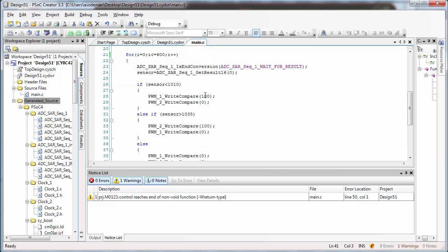So think about first what you would expect to happen. For example, if I would change this from 100 to 80, I would expect this to improve the stability of the move. So the overshoot should go down, but it should also make the move slower. So that means that the rise time should increase. Try this and do the calculations again and see what you get.